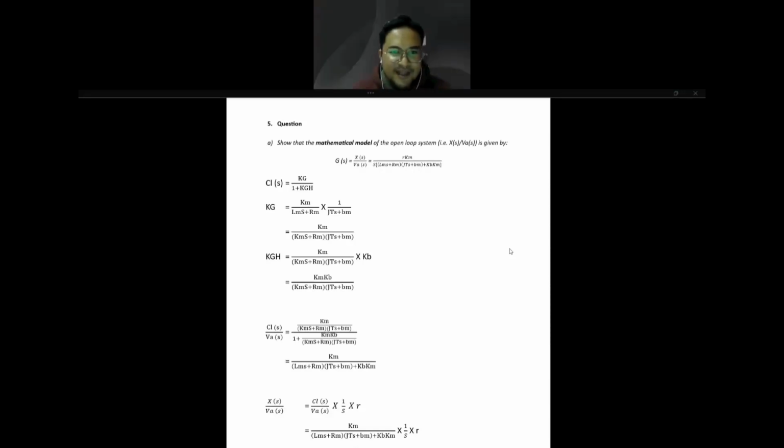Thank you, Mos. To begin our analysis, we first had to derive the open loop transfer function. As you can see on the screen, the system consists of a DC armature-controlled motor where the drive bar moves a linear slide table. Based on the block diagram in figure 2, we identified three main stages. The electrical component represented by the gain Km over the impedance.